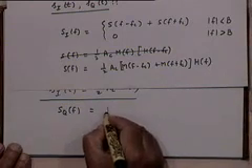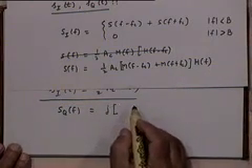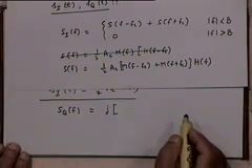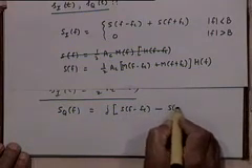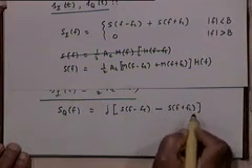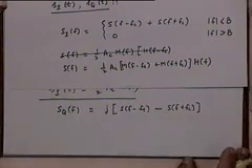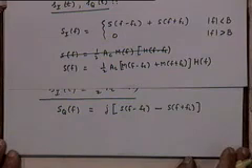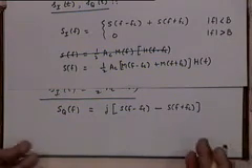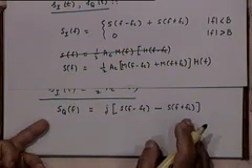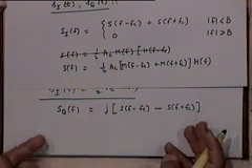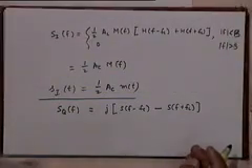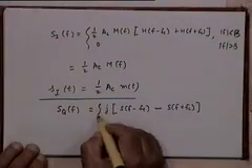So it will be now, instead of S(f − fc) + S(f + fc), it will be j times [S(f − fc) − S(f + fc)]. Just remember what is sin 2π fc t. It is e^(j2π fc t) minus e^(−j2π fc t) divided by 2j, right? Use that result, use the frequency translation theorem of the Fourier transform, and this is what you get. Straightforward, right? So this will be the result.